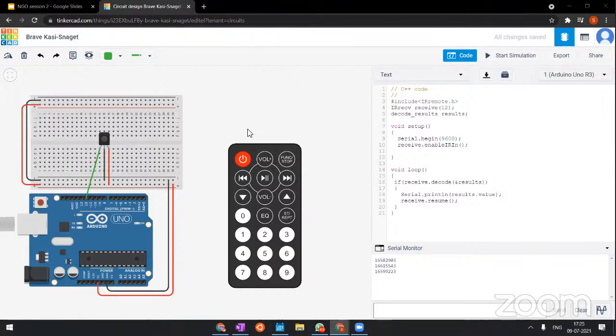Like, from the signal that your remote sends, it will tell you what company signal it is. So basically, yes, in a remote, all buttons will have a unique signal. But sometimes you might have different manufacturers having the same signal for a particular key. So that's why you might have noticed that some of your remotes might be able to control another device that it is not meant to control. That is essentially because all it is doing is sending the same IR signal that the receiver is expecting to receive.